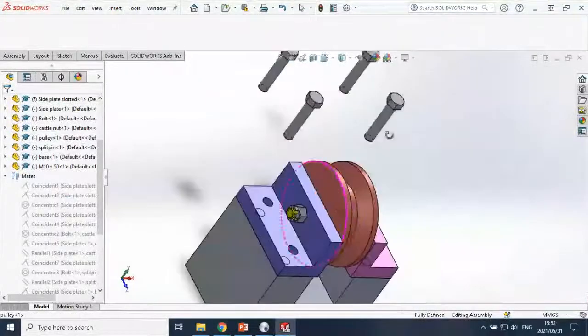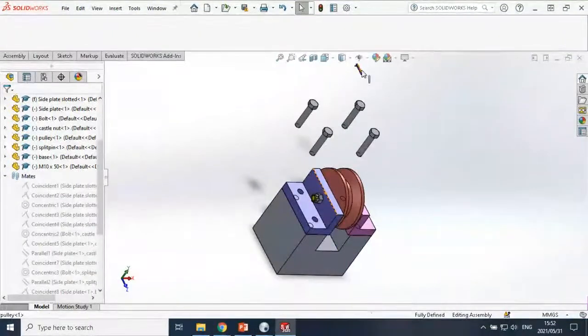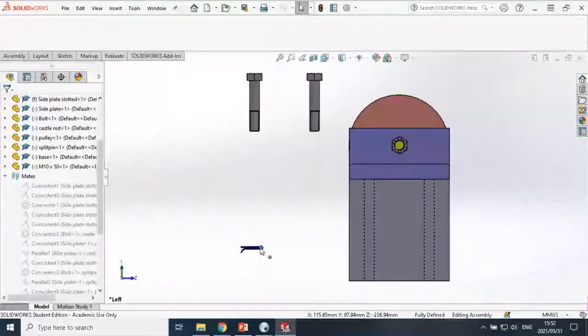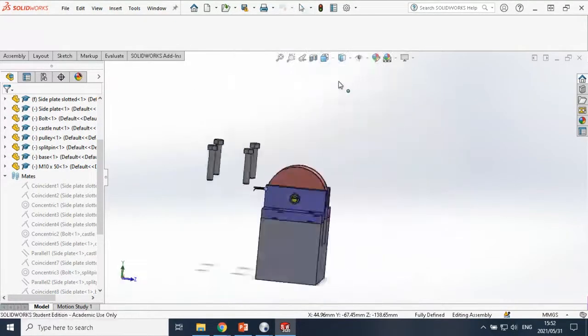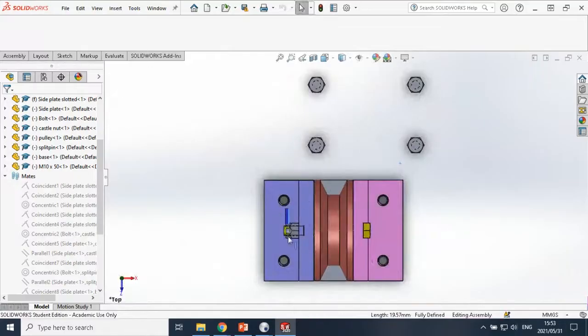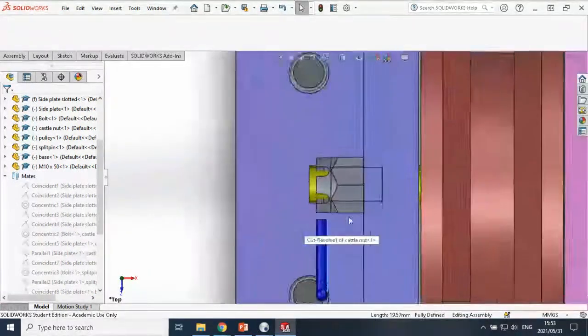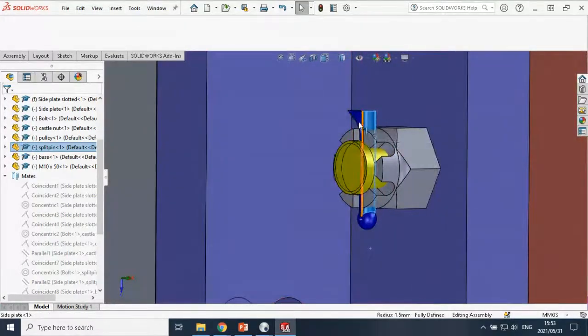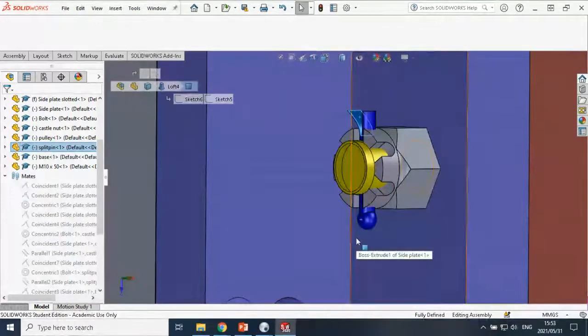Okay, then castle nut also usually has a split pin somewhere. Okay, so the split pin gets pushed through, and then once it's through the hole, we bend it open on the other side to make sure that it won't fall out by itself.